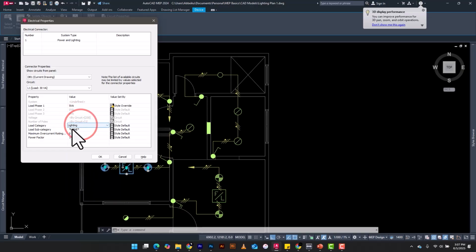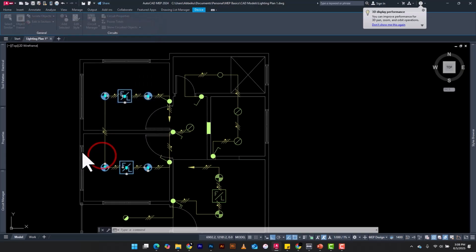And the sub load category, I'm going to leave that empty because the only option I have here is motor. The overcurrent protection that we are going to use for this is 10, like I specified over there, and power factor I'll use 0.8. Don't forget this should appear in all our dealing. So 0.8, that's it. I'm going to select okay.